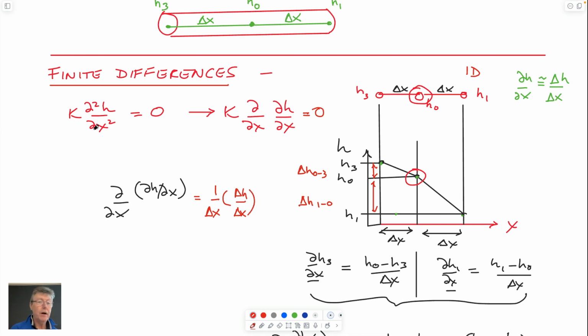So we're writing this second order partial differential as to what it is by splitting it out in longhand, identifying each of these components as finite derivatives, not partial derivatives, and then trying to figure out exactly what these are. So we can take this portion first. If we want to get the change in head with length, we can do it on this portion here. So dh1 over dx would be the head change over the length. So it would be the head change between this node and this node, which is just this. All is written in the convention from upstream minus downstream, so we can get our gradients in the right order.